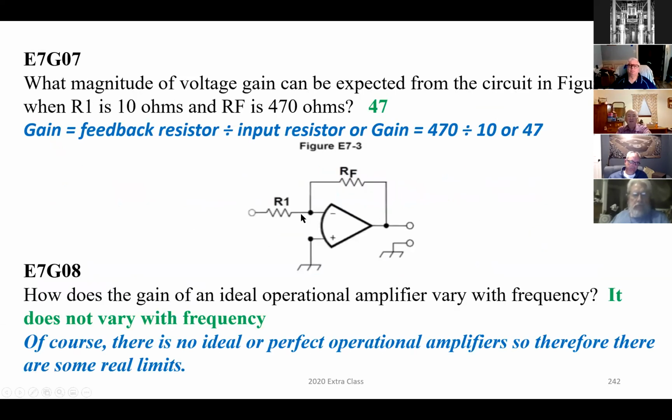You know, if we look, we're feeding the op amp on the negative side. So it's going to invert that signal. If we fed it on the positive side, then it would actually become a positive gain instead of a negative.